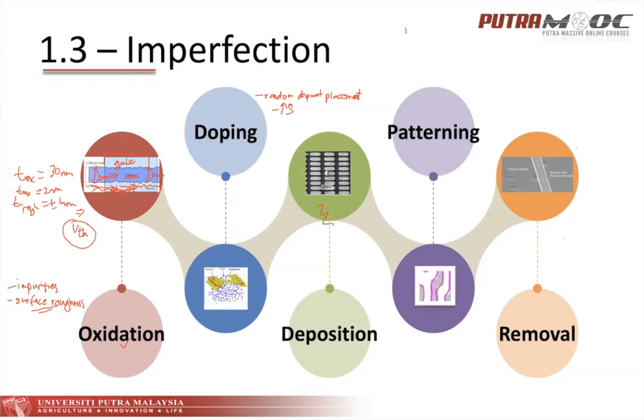So all the transistors that we fabricate will produce 0.2 volt or maybe plus minus sikit je lah, alright? For example, we want to fabricate 0.2 volt. Suddenly, one that we fabricate is 0.05 volt and another extreme end would be like 0.5 volt. So we don't want this very large variation in the threshold voltage, which is introduced during the doping process. Okay, is there any question?